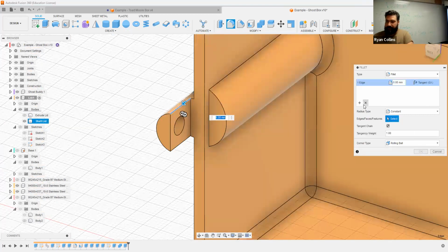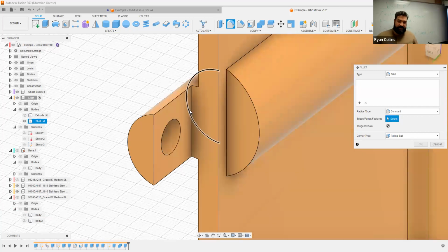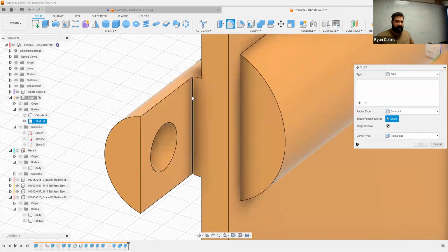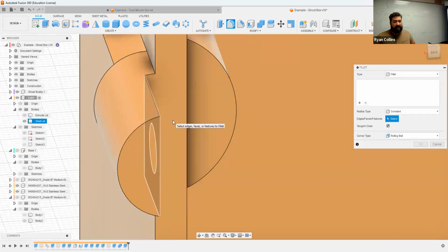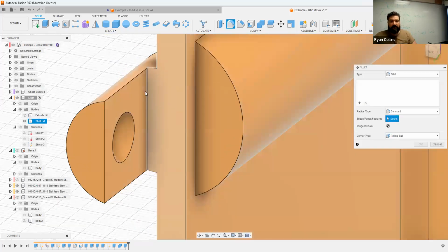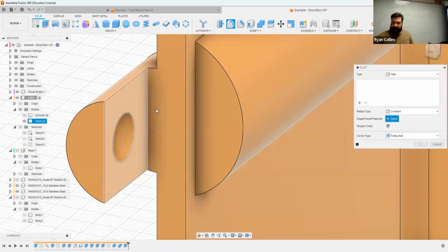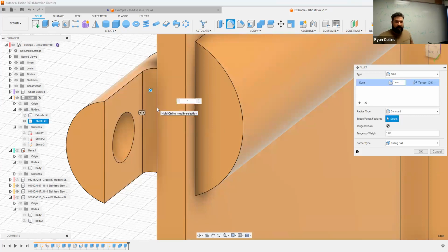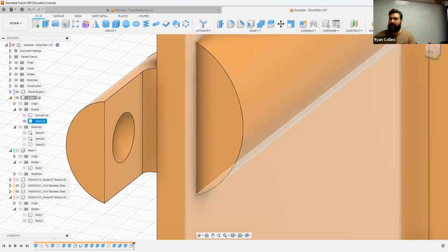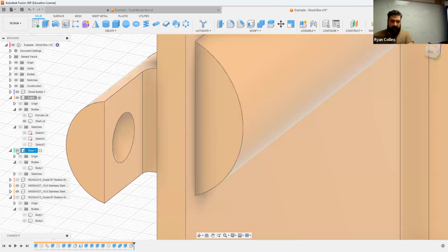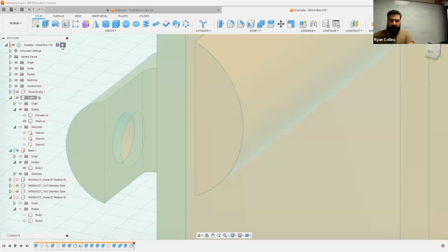But before I do that, remember one thing you want to do. This little angle here definitely creates a weak point. Now, this whole tab here is way thicker than I would normally make something like this. But what you want to do is add a fillet right there, just a little bit, like even the 1 millimeter right there. That little bit of a curvature will strengthen this tab. Select OK. So now let me unhide the base, open the whole thing.